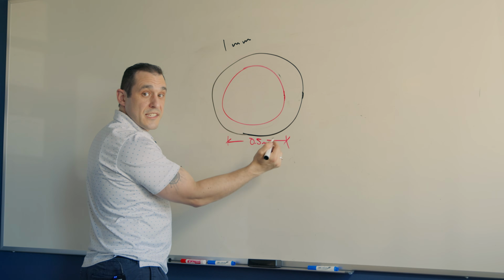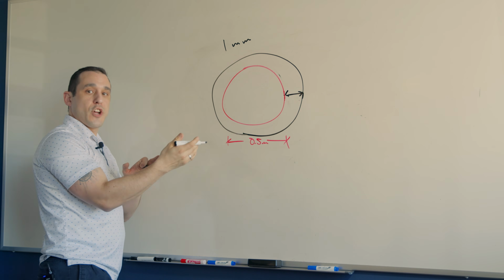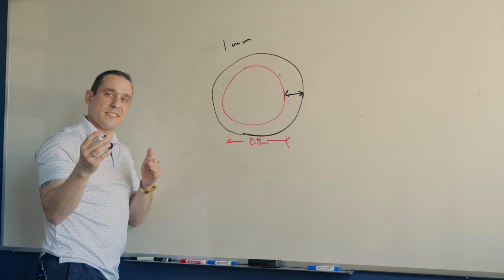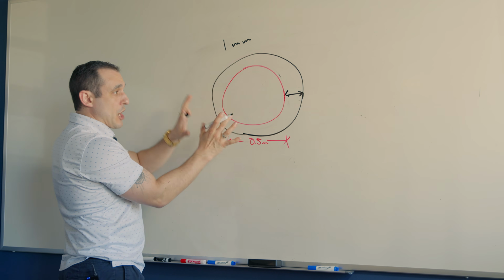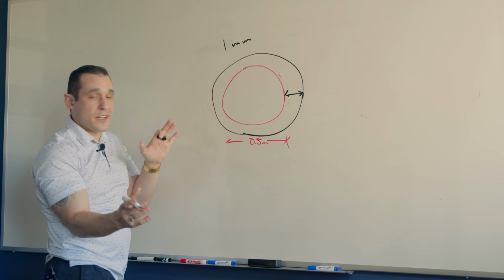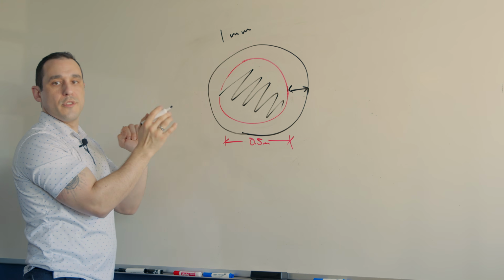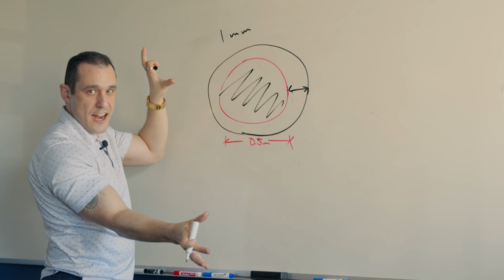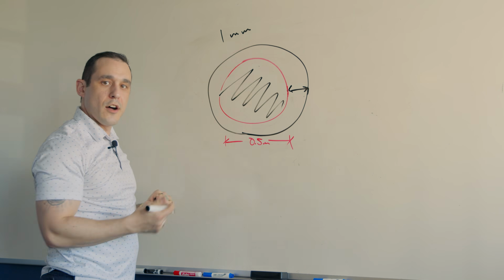Now there will be some distance between the edge of the solder mask opening and the edge of the copper pad that's hidden by the solder mask. But we don't typically set this to some value like exactly 1 mil or 2 mil. We can kind of set the copper pad size to be whatever we want. All that matters is that we leave enough copper exposed through this solder mask opening, and we have that consistently across the entire BGA footprint in order to ensure consistent soldering of that BGA onto the PCB.